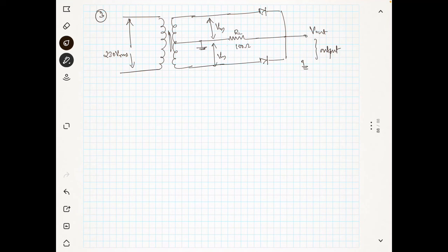It is asked to find a lot of things. The frequency is also given. The frequency input was 50 Hertz. So the first part of the problem is to obtain the output frequency. The second part of the problem is to obtain the peak voltage Vm, and the turns ratio is given, I forgot to write it, it is 5:1.